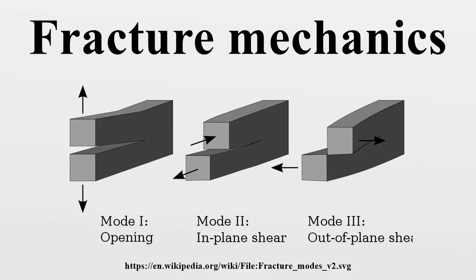The parameter T also significantly influences the fracture initiation in brittle materials using the maximum tangential strain fracture criterion, as found by the researchers at Texas A&M University. It is found that both parameter T and Poisson's ratio of the material play important roles in prediction of the crack propagation angle and the mixed mode fracture toughness of the materials.